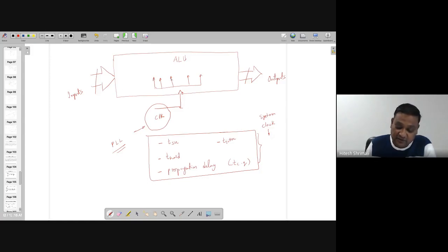And for running the output at such a high speed, you need to have W/L very high. This is the general concept. If you are increasing it, capacitive load is going to increase, resistance decreases, of course, but it's not only positive things that come; there are lots of negative parts coming because of this.